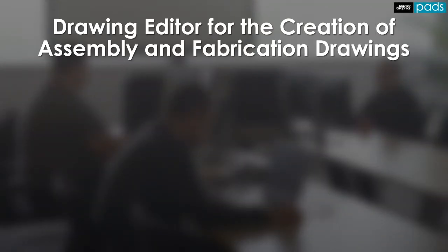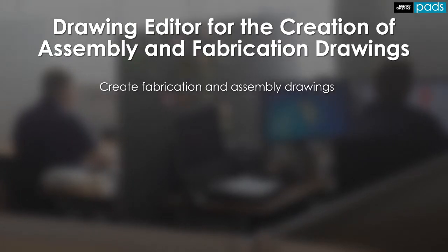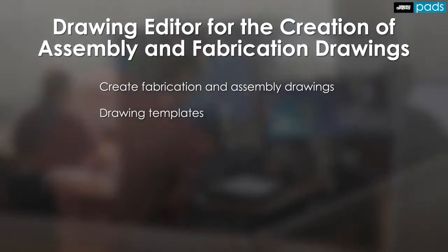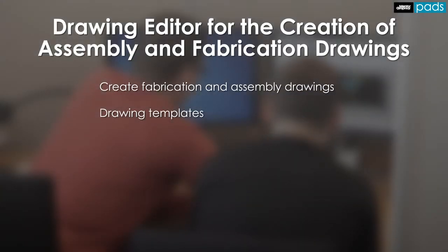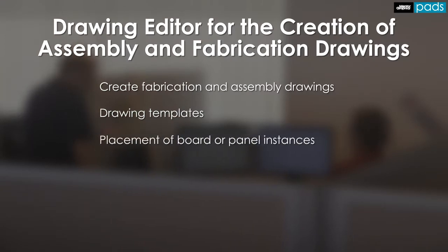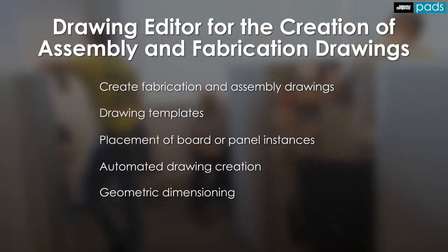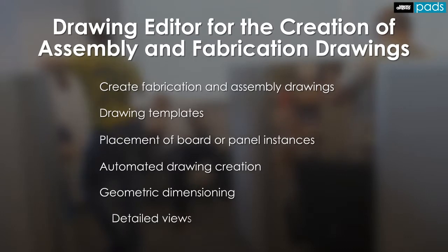The drawing editor provides an environment for the creation of multi-sheet PCB fabrication and assembly drawings. Drawings may be created using customized templates, allowing common details to be added automatically that adhere to company and industry standards. PCBs or panels may be placed on sheets, notes added, drill drawings completed, and title blocks updated using a menu-driven automated interface. Geometric dimensioning and tolerancing provides for precise definition of the fabrication specifications.